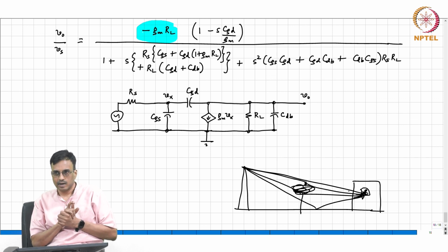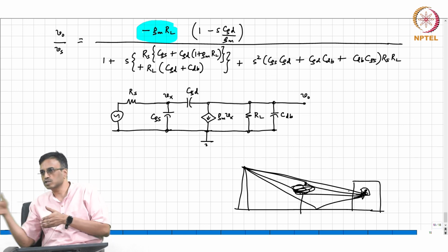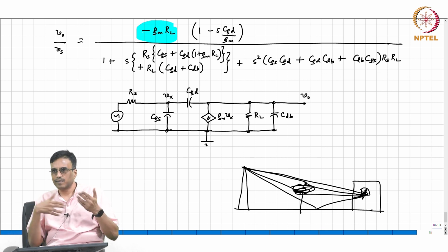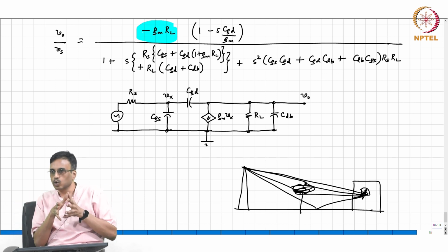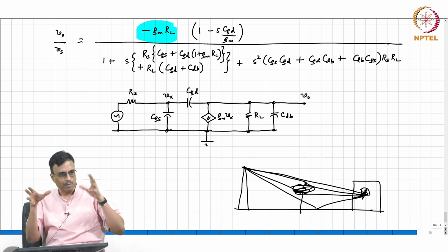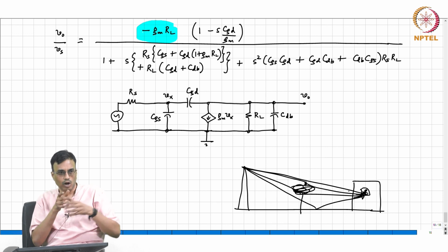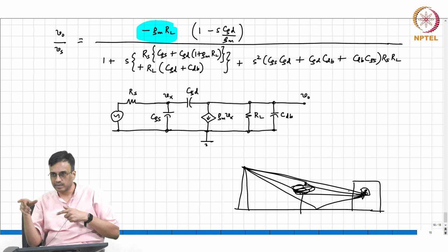You understand, right? Which is why, if you are not getting any signal, you just move a foot away, and then suddenly the signal becomes all right. So, how is that possible? If you move slightly, what happens? The phase of each path now is different. For many numbers to add to 0, those numbers must be related in a very special way. These are all complex numbers, because they all have magnitude and phase.